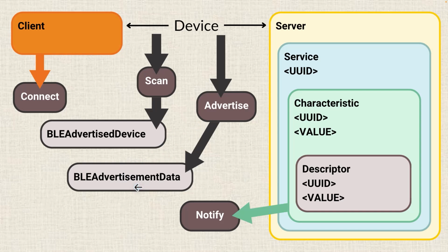We can say, hey, always show this stuff. And then we could say, well, only show this stuff if somebody's asking for it or actively scanning for it. So basically, we can set advertisement data and then we can set scan response data. Now, in order to handle the advertisement data, we've got objects inside the library called BLE Advertisement Data. That's the name of the data structure that we can use.